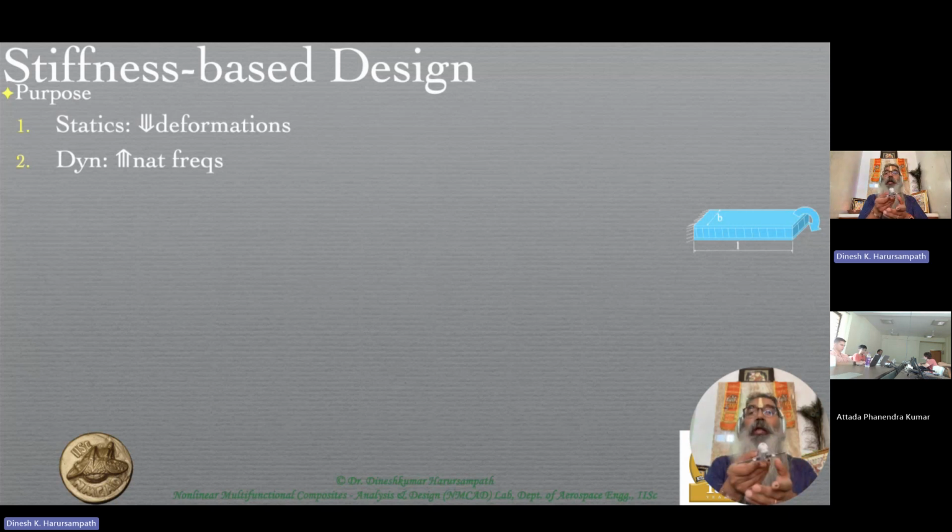On the other hand, in a helicopter rotor blade, you have two sticks. One is called the cyclic pitch stick, and the other is called the collective pitch stick. The collective pitch stick, when you lift it up, typically for a right-handed person, it will be on the left, and essentially you're lifting that stick. For all the rotor blades, it might be a four-bladed rotor, for example, all the rotor blades will increase their pitch by the same amount. In other words, they will change their angle of attack by the same amount.